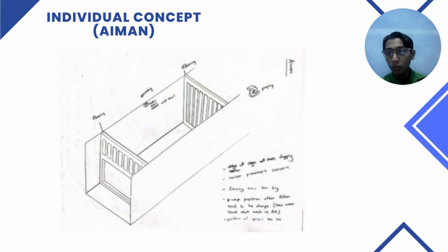For flowing, a front barrier is created which consists of a railing type design at the upper part and a big hole at the bottom part. The purpose of such a design is to allow the big waste to go into the big hole while the top part filters the waste and allows only water to flow through. For filtering, the rear barrier is created which consists of only a railing-like design. This is to trap the waste from escaping, thus preventing waste from flowing through it.